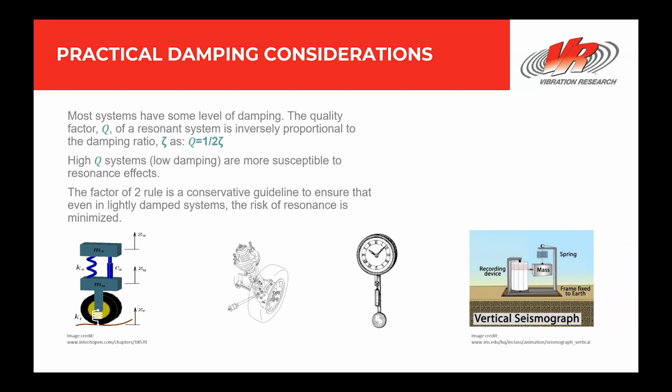For critically damped, where zeta is equal to 1, we can think of automotive shock absorbers, which are designed to quickly return the vehicle to a stable state after disturbance, like hitting a pothole, without oscillating. This ensures a smooth ride and quick stabilization. Or we could think of door closers, the mechanism that ensures that a door closes smoothly and quickly without bouncing back.